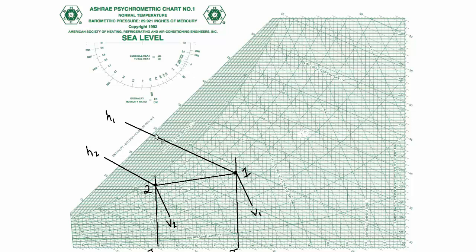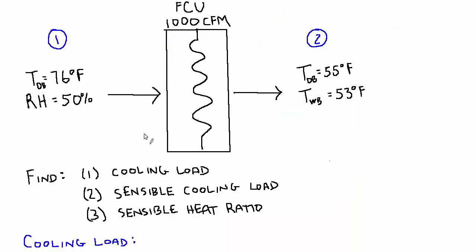So as far as picking these values, you can pick them directly off the chart. I put them into a psychrometric calculator to be extra precise for the sake of what we're trying to achieve here, which is understanding exactly how much error gets introduced by being a bit hand wavy in your assumptions. So I don't want to be hand wavy in the selection of those values off the chart, which is a pretty big source of error. If you're really rushing, you could round off and certainly introduce a couple of percent error just by picking the enthalpy without a really keen eye.